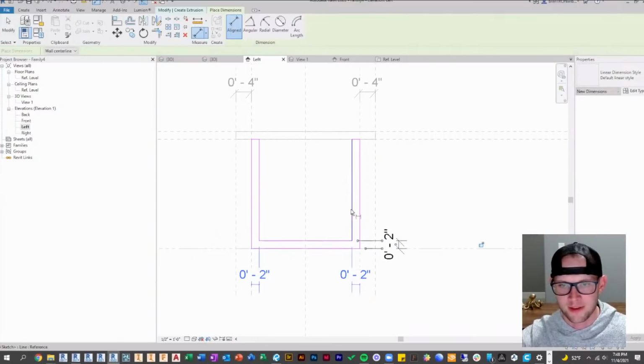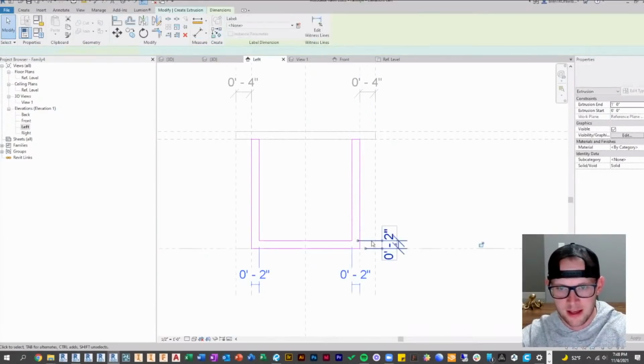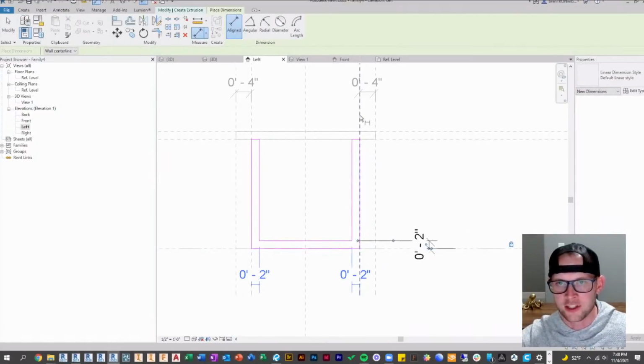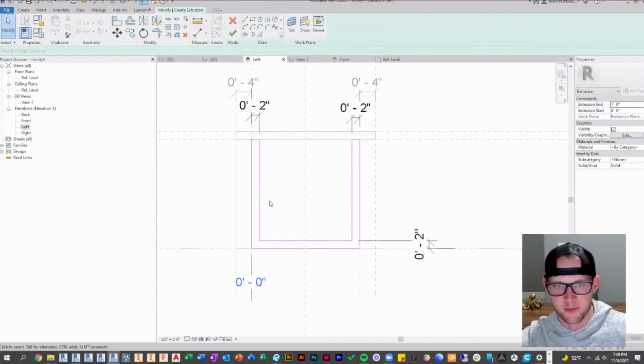Okay, here I'm going to do something I maybe just told you not to do. I'm going to constrain geometry. Actually, I'm going to constrain the reference plane and the sketch. I just make sure I'm getting the reference plane. That way it's still constrained to this reference plane and not the geometry. If you're not being careful, you'll just click like this, like I was originally trying to do. And that's a bad idea, in my opinion.